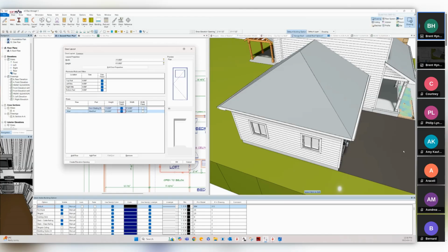And next thing I'm going to do, I'm going to go to add row again. So down below. Okay. And in this case, it put it in as a door glazing, but I'm going to change that to a panel. Okay. And its height is going to be flexible. So that's where if we were to change this door from a 6'8" door to an 8-foot door, it's going to expand for me. The window doesn't, and the rails and stiles don't either. So this has to have some sort of movement in it.